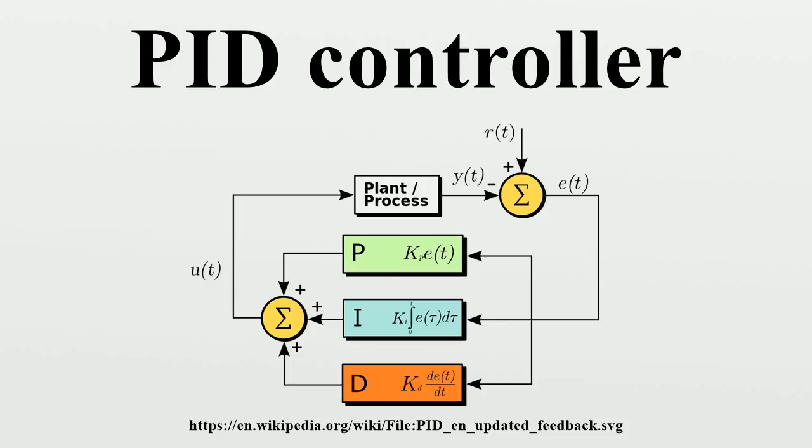Trials were carried out on the USS New Mexico, with the controller controlling the angular velocity of the rudder. PI control yielded sustained yaw of plus or minus 2 degrees. Adding the D element yielded a yaw error of plus or minus 1/6 of a degree, better than most helmsmen could achieve. The Navy ultimately did not adopt the system, due to resistance by personnel. Similar work was carried out and published by several others in the 1930s.